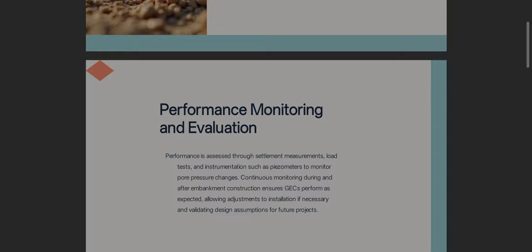Objectives of performance monitoring. The primary objectives of monitoring GEC supported ground include assessing settlement behavior, evaluating load transfer mechanisms between the columns and surrounding soil, and observing the dissipation of excess pore water pressure.